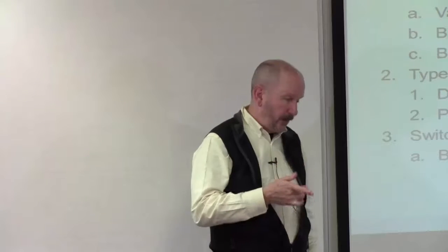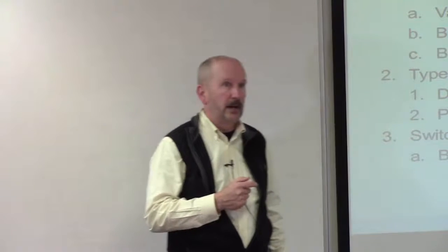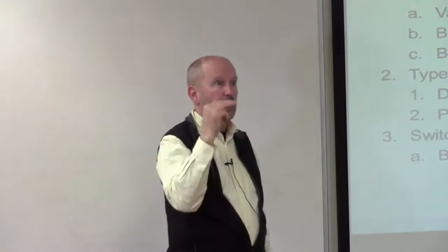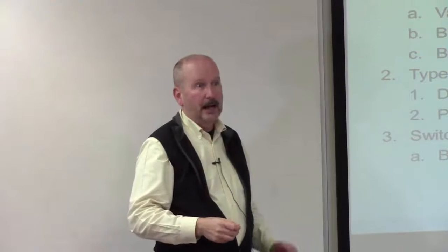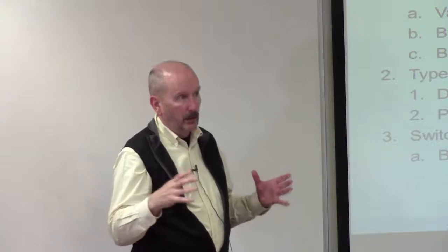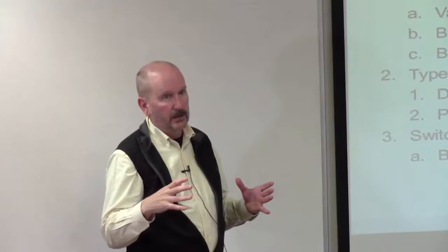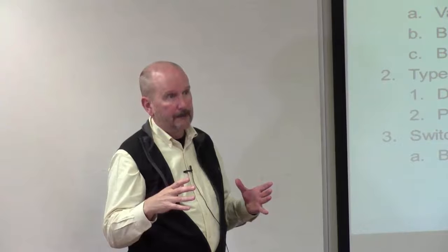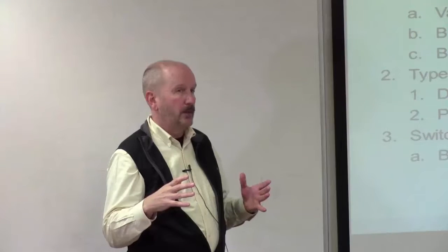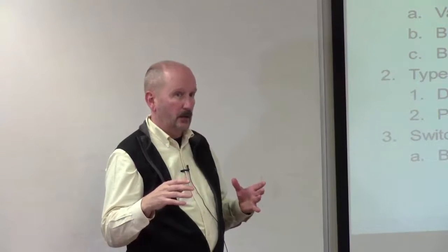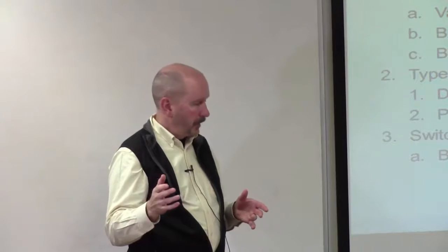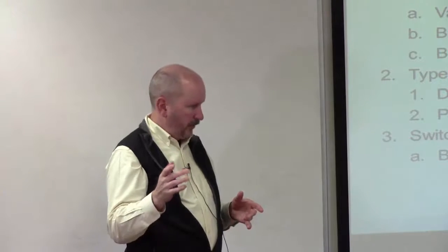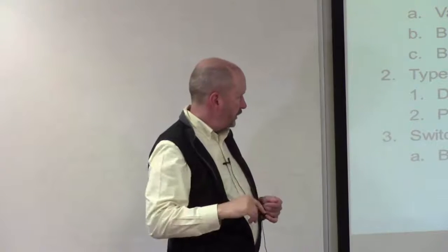The tallest A-frame that I have ever seen is 108 feet tall, and the connection point's about 104 feet up. That is a really big structure, and it has correspondingly large foundations for each of the legs. Okay? If you can come up with a design that does not need such tall structures, you'll save a bunch of money. Give me just a moment, and I'll show you this substation that has this.